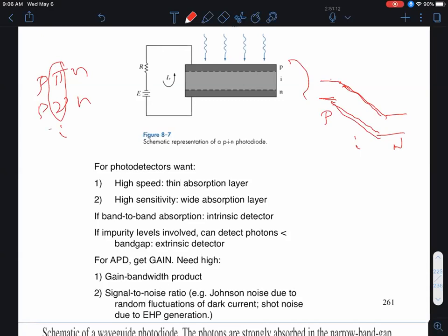In a regular PN junction, although we draw them kind of linear, if it's a step junction, it's really a parabolic shape joining smoothly to another parabolic shape. So it's not really linear. It's two parabolas which join smoothly. Approximately looks linear. But in the case of a PIN diode, it's exactly linear.